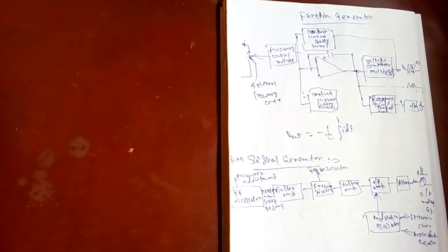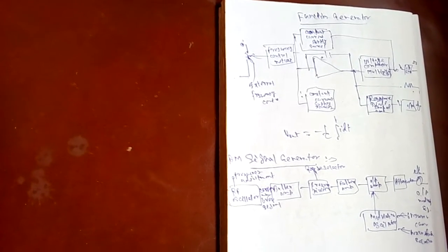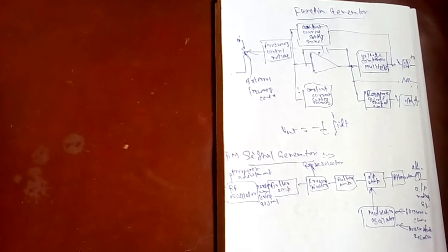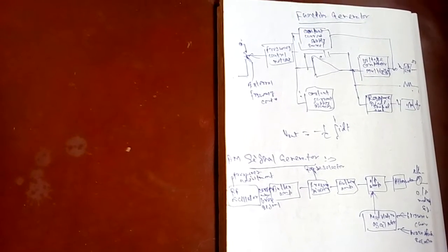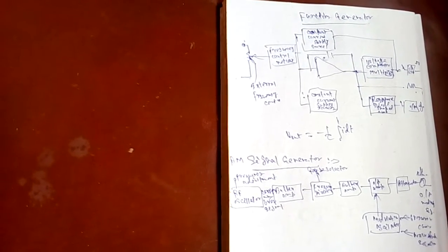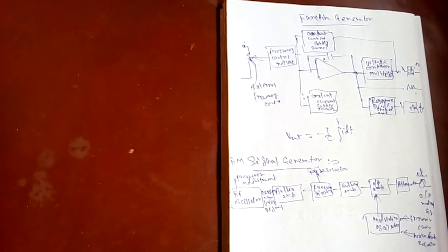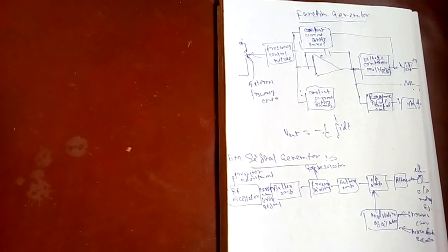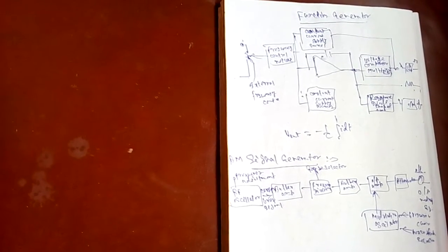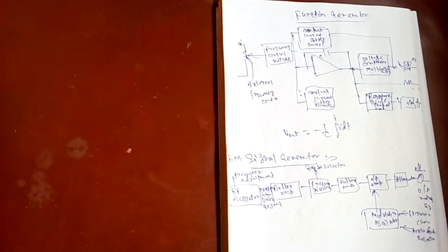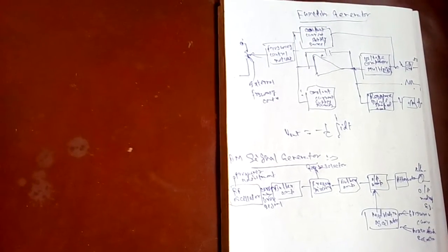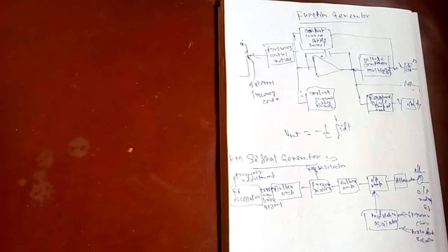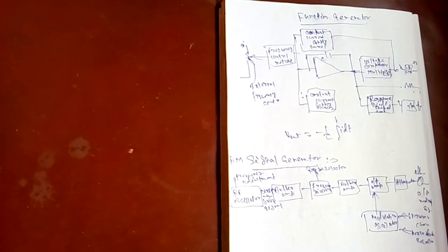The Q factor of the LC circuit should be very high, above 20,000, which can be achieved with a crystal oscillator in place of an LC oscillator. The audio frequency signal is generated by another very stable source called the modulating oscillator. The position of the modulating oscillator changes the frequency and the amplitude of the signal being generated. This oscillator can produce various types of waveforms: square, triangular, pulses. So the radio frequency and the modulation frequency are fed to the wideband amplifier called the output amplifier.